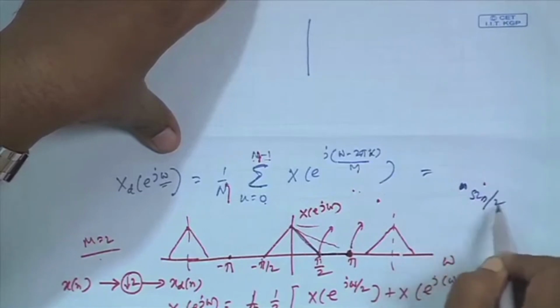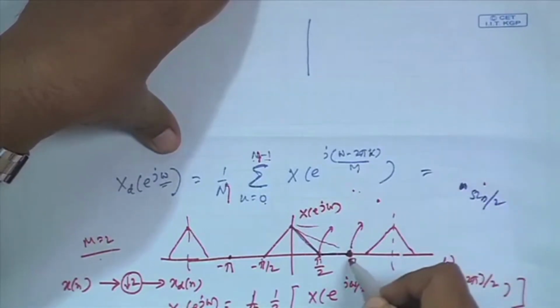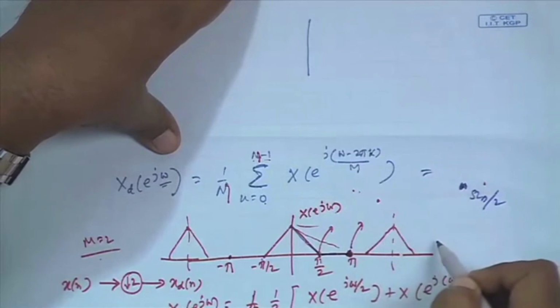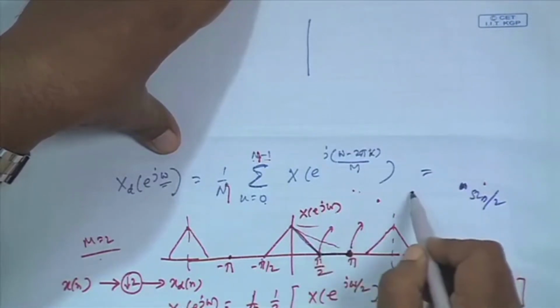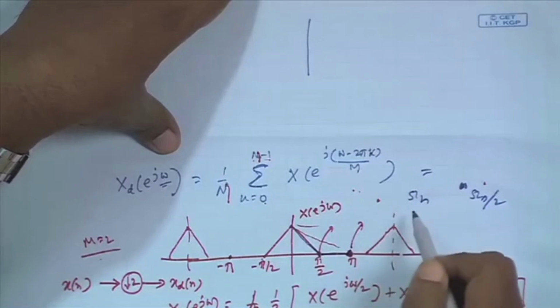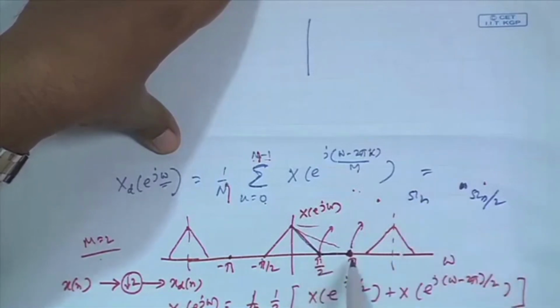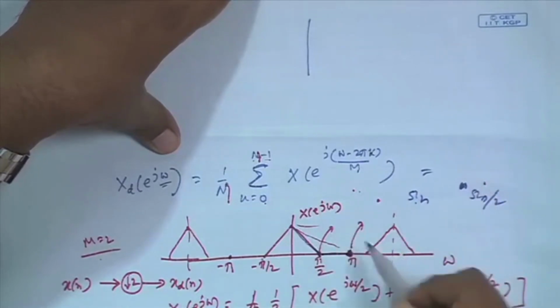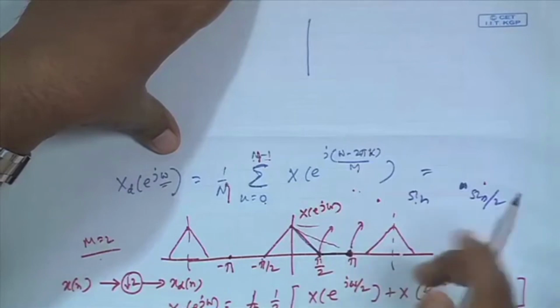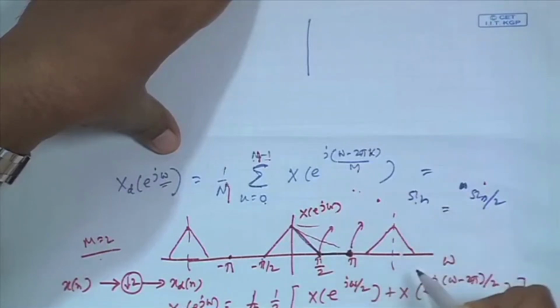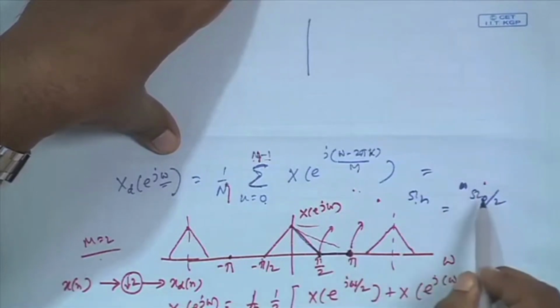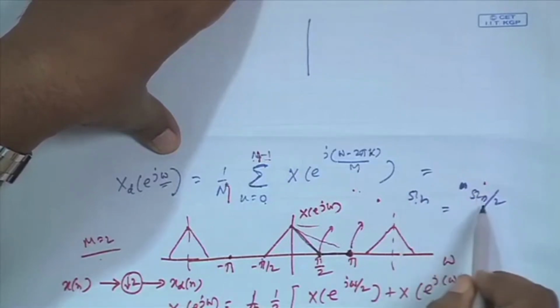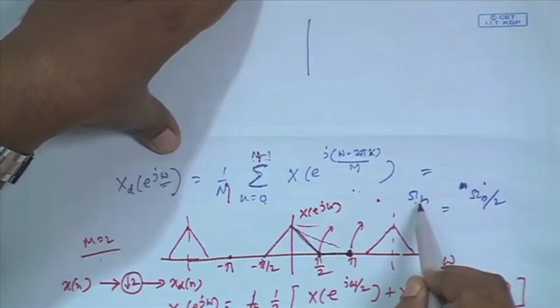Okay, omega s by 2 analog will map to this digital always, irrespective of what omega s by 2 is. And this corresponds to the band limiting frequency omega h. Now, since pi by 2 is half of pi, omega h is obviously half of omega s by 2 in this. But to avoid aliasing, it is enough if omega h is equal to omega s by 2. That is, this pi by 2 goes up to pi, which means omega s by 2 is unnecessarily twice omega h. The sampling rate could be brought down by 2, so that omega s by 2 is actually omega h.